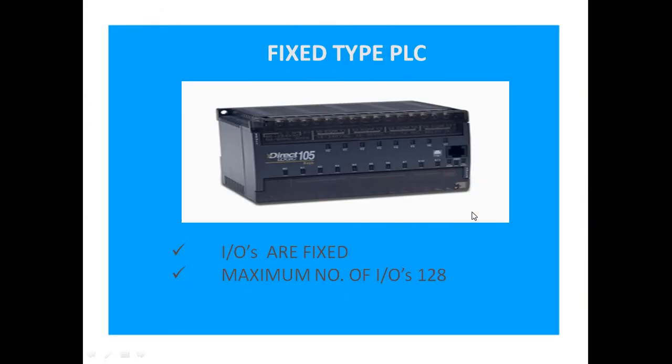This is the fixed type PLC. Here the IOs cannot be expanded, that is, they are fixed. This type of PLC is used in small process where the less number of inputs and outputs are required, and here the maximum number of inputs output is 128.